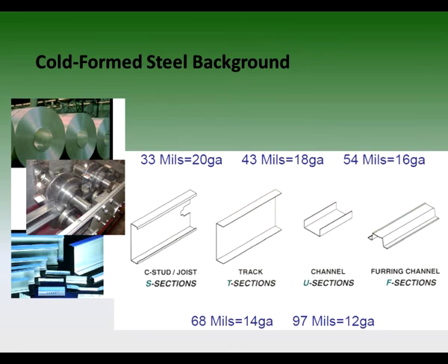Sheet steel that is used for CFS studs and other products is protected by a coating and then shipped from the mill in coils. The industry standard for corrosion resistance is galvanization, which means coating the steel in zinc. The upper picture here shows galvanized coils of steel that are ready to leave the steel mill. There are other coatings that are also used to provide protection against corrosion, although galvanization is the most common process.